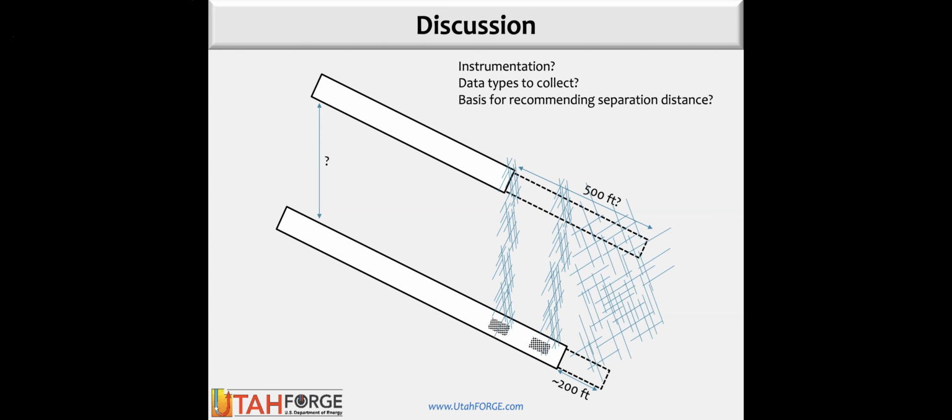So, essentially what some of my models are saying is that if you allow for a little bit more cooling of the water coming out of the production well, but yet still are producing high enough enthalpy to make power from it, you can end up in a scenario where you actually get significantly more power out of the subsurface just by allowing a little bit more temperature decline. In terms of a thermodynamics or thermal conductivity perspective, the physics of why are pretty straightforward. Does that make sense?